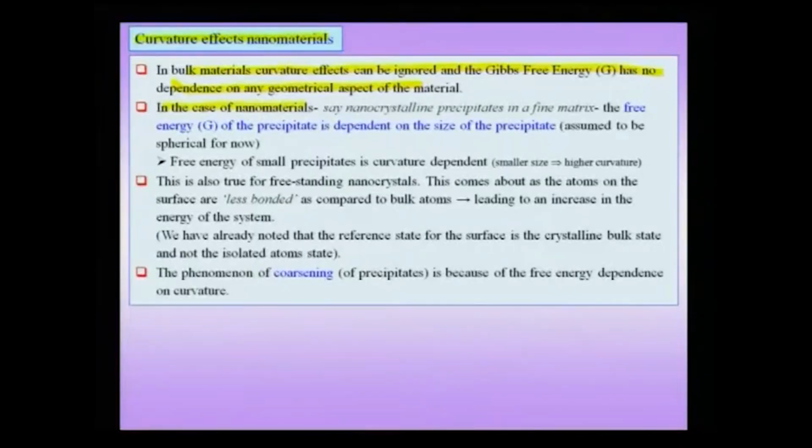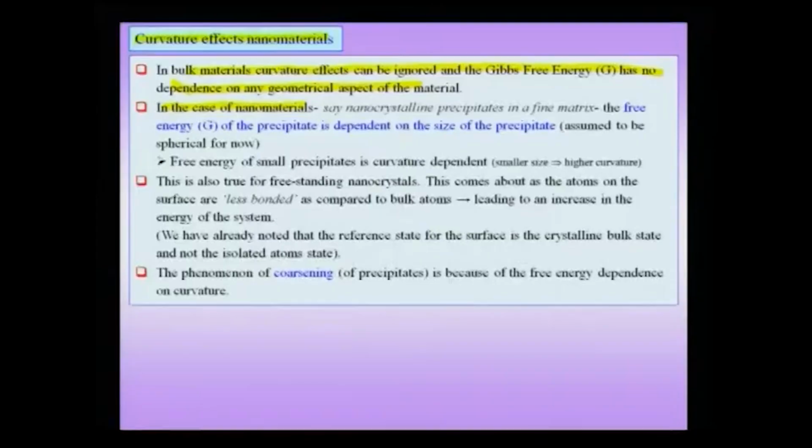In the case of nanomaterials, and typically I am here talking about nanoparticles or nanocrystalline materials where the grain size is on the nano scale, then we are actually dealing with certain interfaces, like a grain boundary or a free surface. For example, I will talk about a particular example which will be used to exemplify the importance of curvature in nanomaterials, which is the case of fine nanocrystalline precipitates in a matrix.